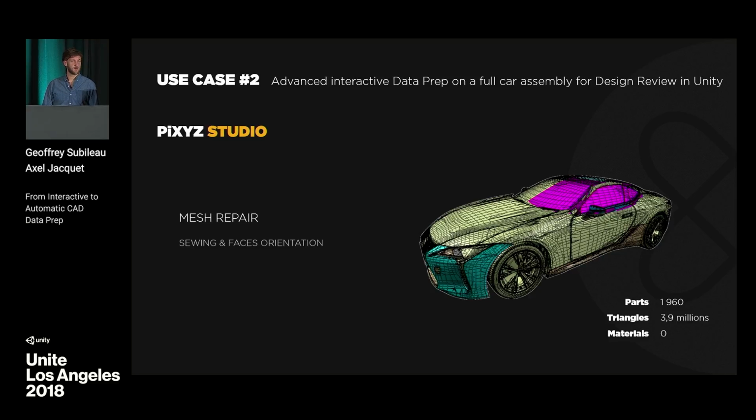And that's why we have a script called Smart Orientation that is perfect for this kind of full car model. It's going to automatically orient all the faces. This powerful feature consists in automatically placing cameras in the cavities of the car, and all the faces will be oriented by simply looking at all the scattered cameras. So a very powerful feature.